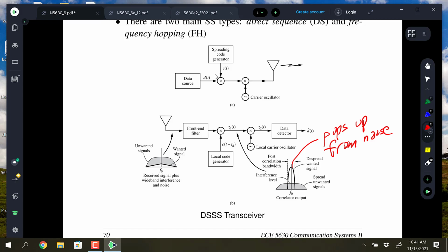And then carrier can be obtained and symbol sync can be obtained later. But usually the despreader can also be related to the symbol sync. The system I worked on for Zigbee, once I got the despreading done, then I also had a symbol rate clock available, and the carrier was done in front of it. The order of things can be different, but frequently you have to despread first because the signal to noise ratio is so poor that that's the only option you have. You can't get a carrier track going and can't get the bit sync going, because you've got to be able to get the signal above the noise floor.